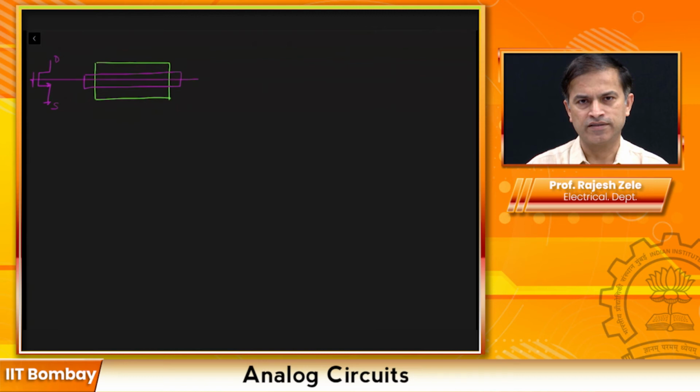So this would be your gate, this would be the drain region, and this would be your source region. This is the way you lay out the transistor. Now if I had to draw 10 more transistors, you would end up drawing these transistors like this, many of them, and there is always a spacing that you need to keep between the transistors so that you don't violate any layout rules.